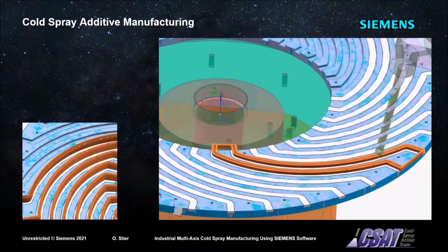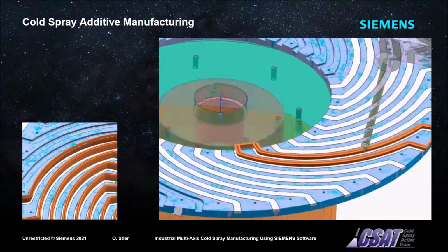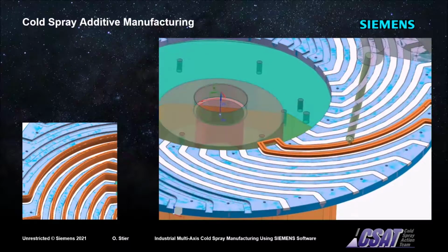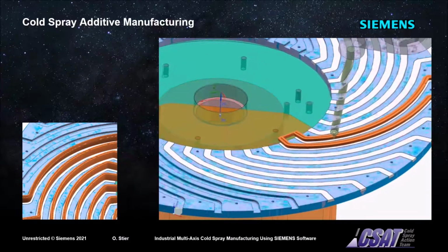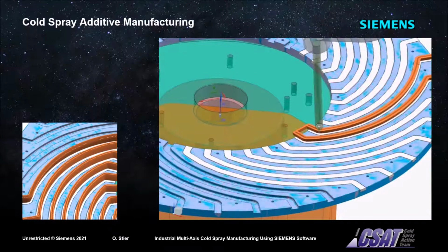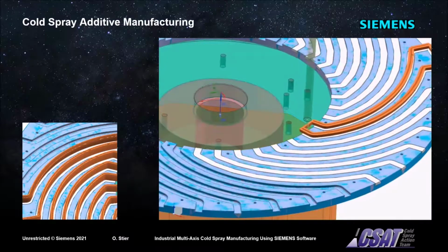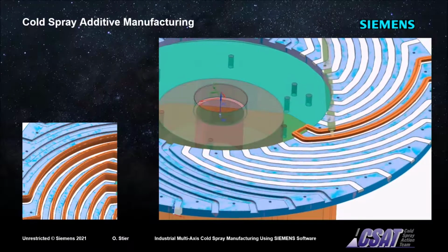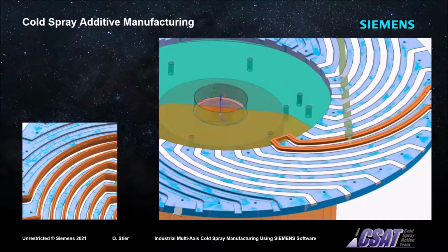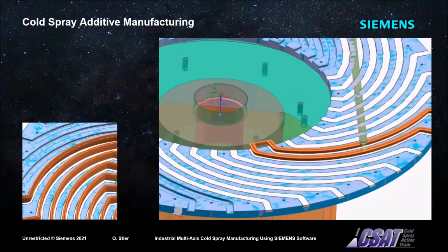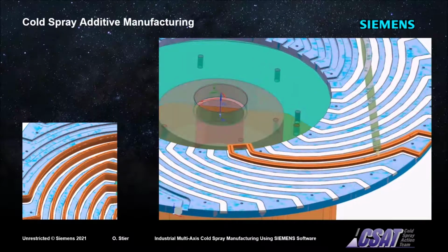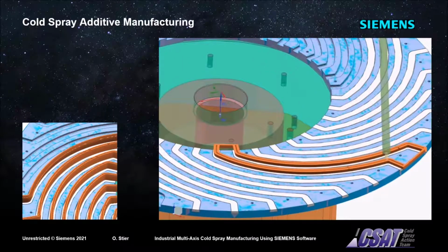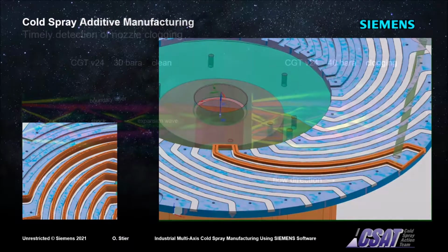Frequent repetition of the shown motion pattern makes the rails grow in height. Hereby, they form vertical walls with a flat top. The resulting cross-section shape is rectangular, with slightly rounded corners and an aspect ratio greater than unity. The tilt angle specification, in connection with uniform rail separation, is crucial for the net shape obtained.